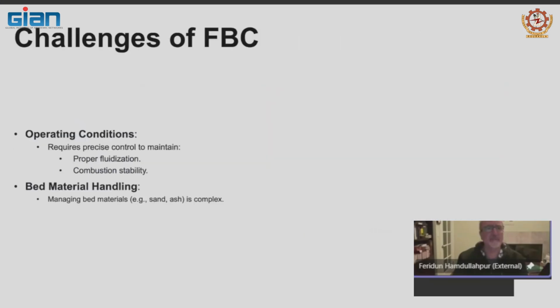All right. What are the challenges when you consider, again, like the room you're in? The size of the room could be the plenum chamber of a bed. It's that size. So to achieve proper fluidization in such a large geometry is extremely difficult. And the schematic I showed you had a partition in it, which divided the bed into two to ease that mixing or achieve better fluidization.